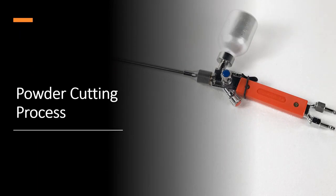Powder cutting is an oxygen cutting process in which a suitable metal powder such as iron powder or mixture of iron and aluminum powder is injected into an oxygen gas stream to assist the cutting action. The powder cutting process is used to cut materials such as stainless steel, cast iron and non-ferrous metals and alloys that cannot be easily cut by oxy-acetylene process. Let us understand the process in detail.